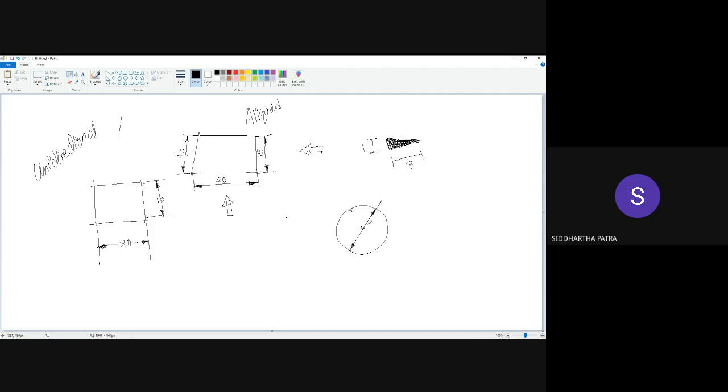So this much represents the diameter, going from one point on the circumference through the center to the opposite point, and this much would contain the arrowheads of the dimension line. Okay, the dimension line extends further, then becomes flat. On top of that, you put phi. This one has a diameter of 20 millimeters, phi 20 as the diameter.